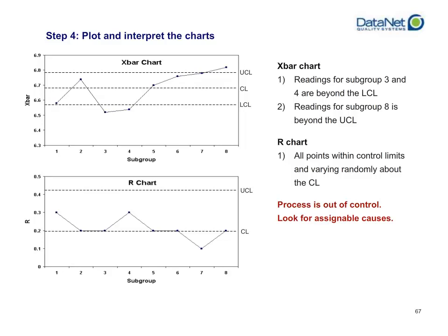For the X-bar chart in this case, your first and second subgroups were falling within your control limits. However, your third and fourth subgroups are out of control. They look like they were actually falling below your lower control limit. Now, it doesn't necessarily mean that you've fallen out of specification, but the process itself has fallen out of control of what historically the data was expected to do. Afterwards, it looks like your process started going back in control again, but once you hit your last subgroup that you plotted, subgroup number 8, you were out of control, violating your upper control limit.